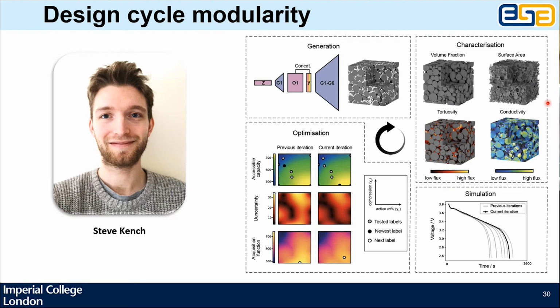The way that we are approaching this is to break it down into a modular system. So rather than trying to do deep manufacture where we learn the entire relationship between every stage at once, what we do instead is the following. We train a conditional GAN, a SliceGAN, and a conditional GAN, unlike the original one, which just learns one type of battery microstructure, a conditional GAN can learn a family of different structures, where each time you also give it a little piece of information about which member of the family it's currently looking at. So I can say to it, okay, have a look at this piece of microstructural image data. And I'm telling you, it was made like this, specified in a few parameters. And so it learns the relationship not just between generating microstructures in general, but generating microstructures of a particular specification, which you specify with manufacturing parameters.